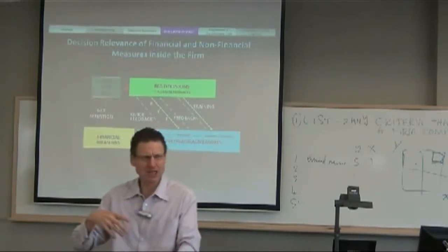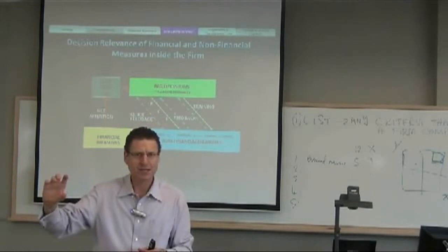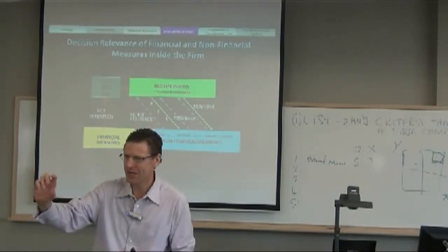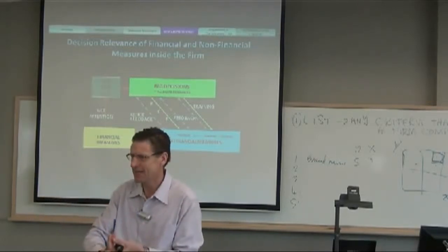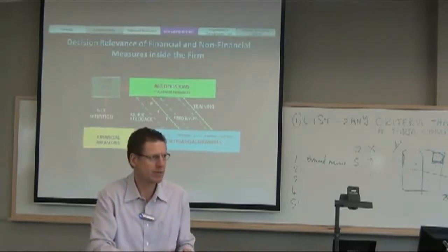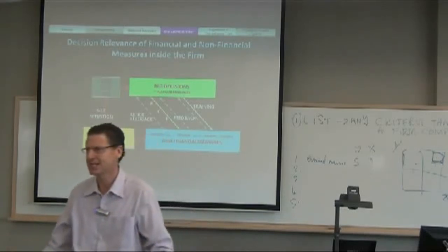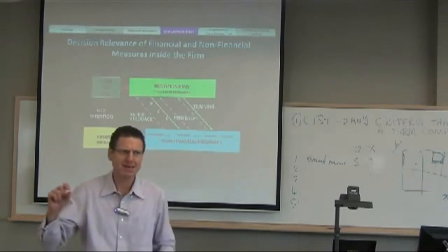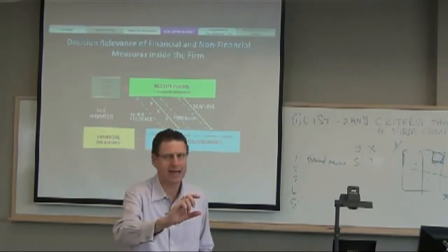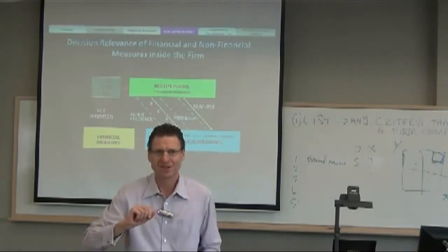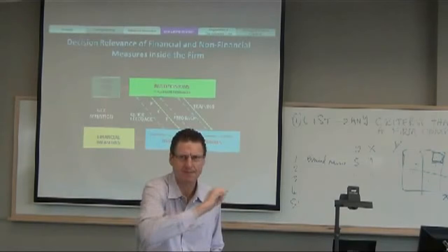So when it comes to production and when it comes to saving money, you just work within the tolerances that customers are happy with. I know you guys strive for excellence, but if you try and make everything perfect, then you can get machine breakdown, you can get bottlenecks, you can get tooling wearing out faster. Lots of things go wrong. So when it comes to the production environment, it's not about making everything perfect. It's about making things consistent within tolerances set, and those tolerances are in line with what the customers want. And this you achieve through control charts. Yeah, control charts help you keep within those tolerances, okay?